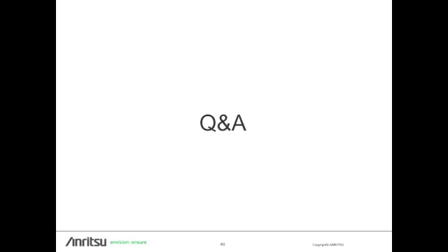Remember we talked about the burst detect mode? That's on the MS2720T and the MT8220T. That's an FFT-based process. The 20,000 traces are done using an FFT.